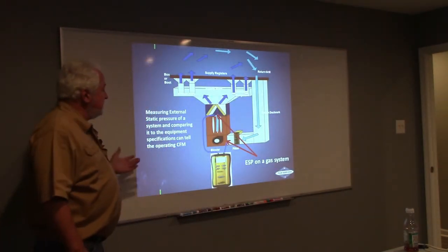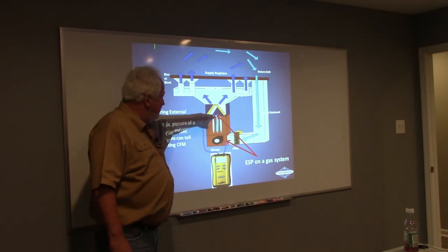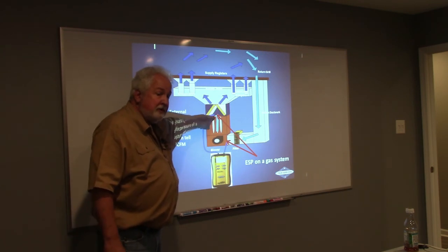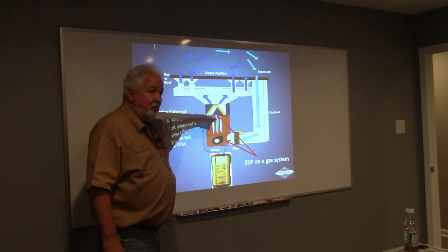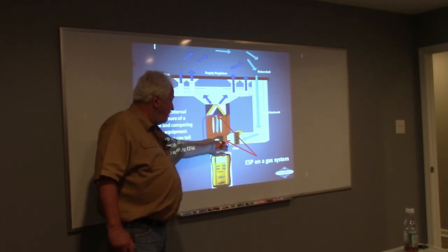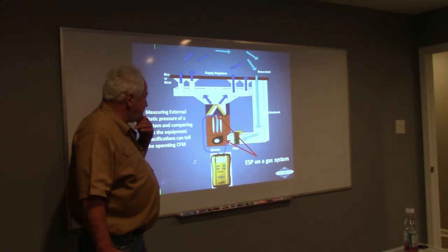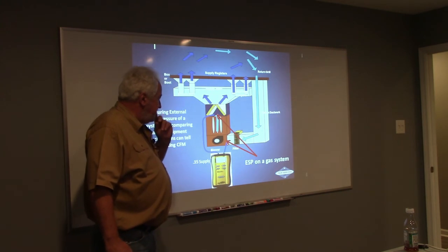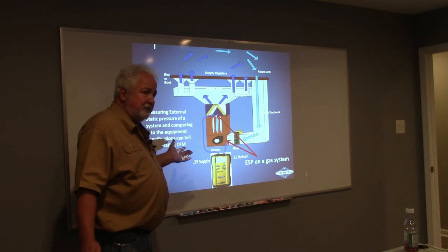All right, so here we go. Here's the same furnace, but instead of horizontal, we're in the upflow position. We're going to measure it right here below the coil, and you saw that all we did was pull the high limit out right there. Pull the high limit out, and you can go in right there. Works out very easily. Do it after the filter, before the blower, right there. So external static pressure on this one, we ended up with 0.35 on our supply, and we ended up with 0.15 on the return. What's going to be the total external static pressure on here?